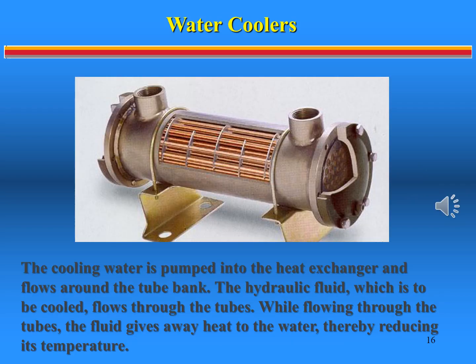Water-cooled systems use cold water to remove heat, with hot and cold fluids separated by a barrier. Compared to air-cooled systems of equivalent capacity, water-cooled systems have lower upfront costs. They also are quiet, compact, and do not alter the surrounding ambient temperature. Variations in air temperature have little or no effect on cooling capacity, which allows for greater consistency. Meanwhile, the system's heated water can be used for other on-site purposes.